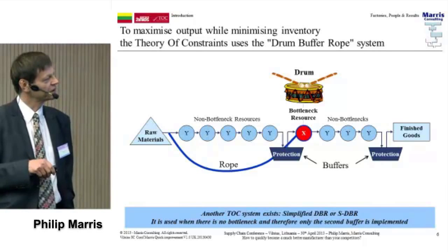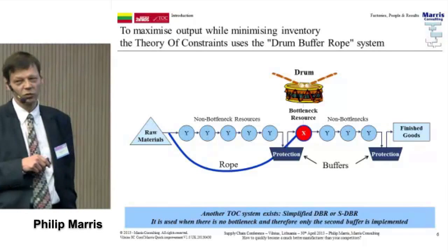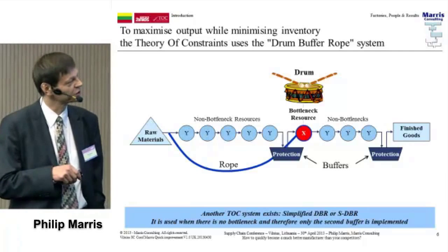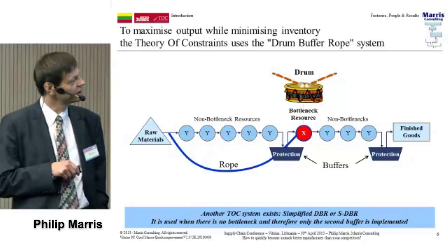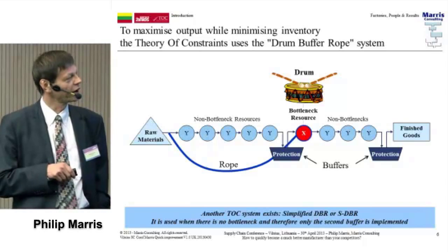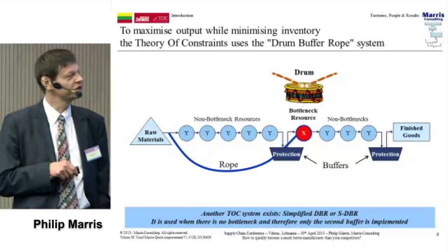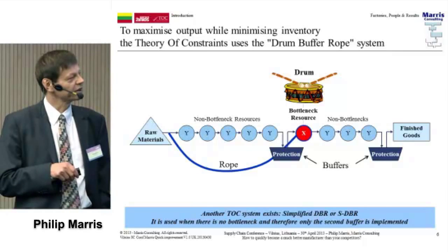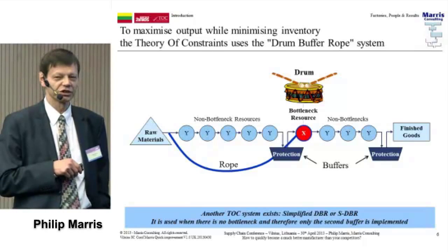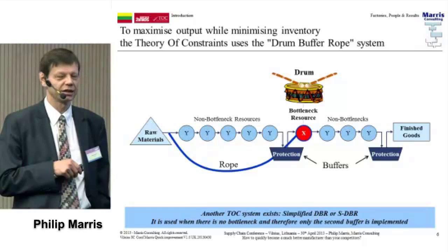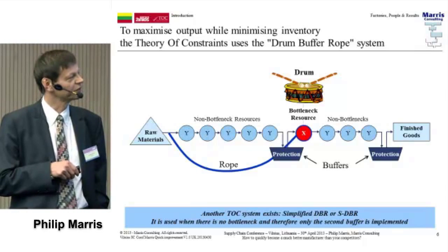The rope is the thing which will decide when one will launch the raw material that corresponds to that particular work order. Okay? So if we assume that these operations will take about 1 hour each, or exactly 1 hour each, then if I want to do that at 16 hours, I will subtract 5 hours of work and I will launch it on the 11th hour. Okay? This is when I said 5 hours, I meant the actual production time.